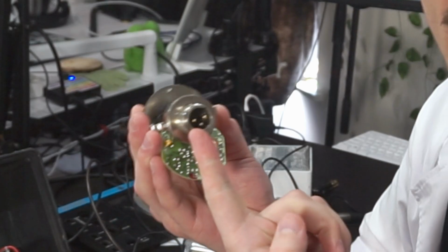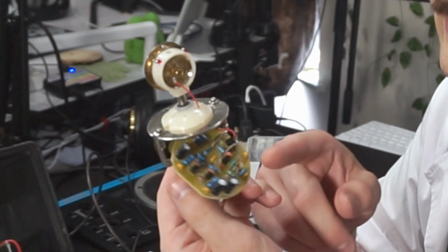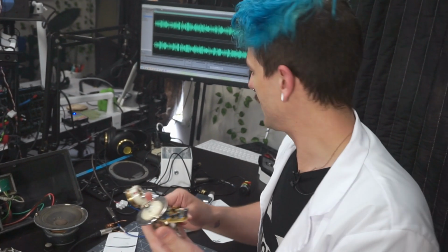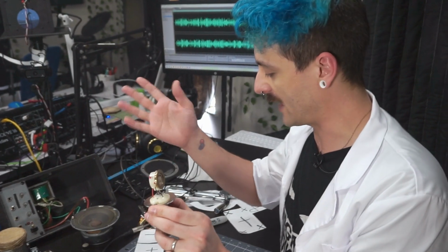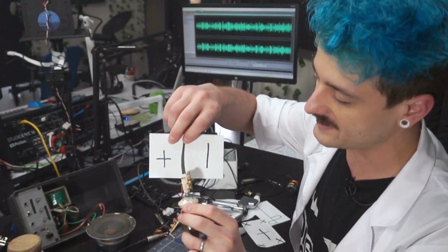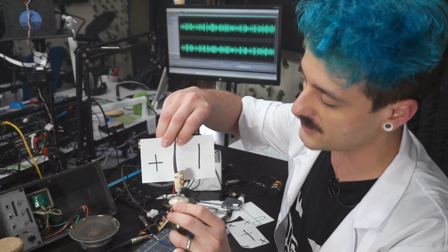Condenser microphones require power fed to them through their XLR connector to power up this circuitry. That's what phantom power is. They're called condenser microphones because that's what we used to call capacitors back in the day. Those two plates are given an opposing charge. So I know this was our magnet from earlier, but imagine one of the plates is charged up positive and one of the plates is charged up negative.